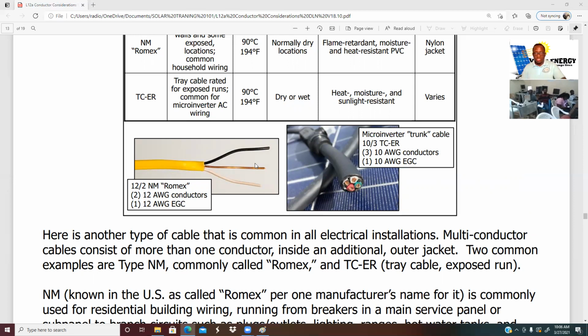Now in Liberia, you see people use this cable to run from one house to another. Not so? Especially the people who do the generator thing, they use the cable to run from one house to another. They say community light. What's going to happen with all the sun shining on this wire? It will break down the jacket, the wire will be exposed. Excellent. So when you're walking down the street and you see such a bad job, what do you think? It was not an experienced person that did it.